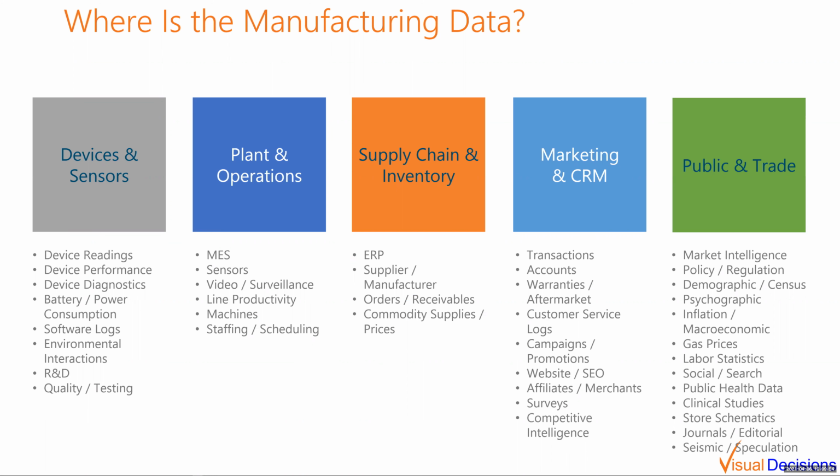So just as a quick example there, if I'm looking at a grinding machine, I may look at the power draw on the grinding wheel in order to determine when I've got too much pressure, my power draw will go up. If I have quality issues and so forth, those might see different spikes or dips in my power consumption and so forth. And so there's a lot of things that I can get just from those devices and sensors.